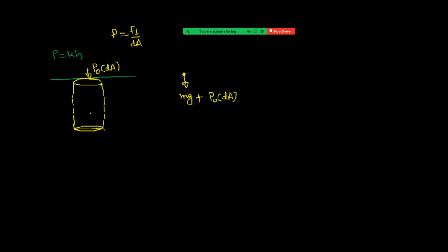Next, by the curved part, that means by the surrounding liquid, force is only along the horizontal and that will get cancelled. Next, by the liquid on the bottom, force will be vertically upwards, equal to pressure at that point into the corresponding area, that is P into A.